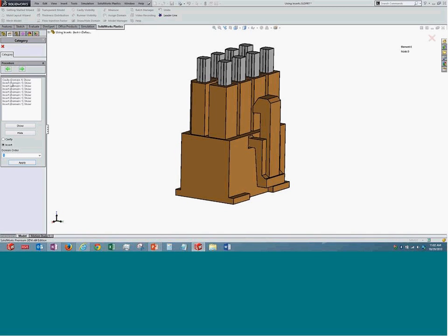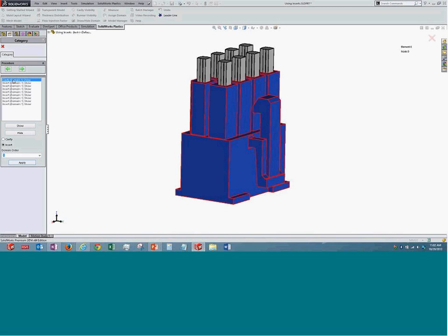Typically, we are going to specify the size of the mesh that is going to be used. A default one is fine. Before, it was just a surface mesh. Here it will take a bit more time because it is more complicated and it needs to fill with solid elements. I have created the mesh. This is how it looks. The color differentiation will help us differentiate the insert and the cavity. Once done, we can proceed further.